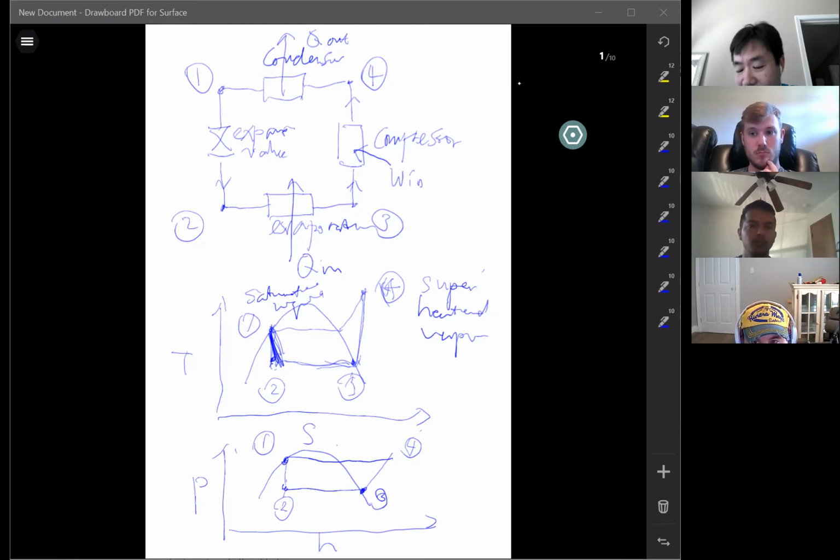Also in reality, you don't measure pressure everywhere to understand the system. There are only 2 pressures in the system, and that's enough. Between the expansion valve before and after, they have the same enthalpy. You don't need to calculate the enthalpy for both of them. You calculate 1, then that's it.